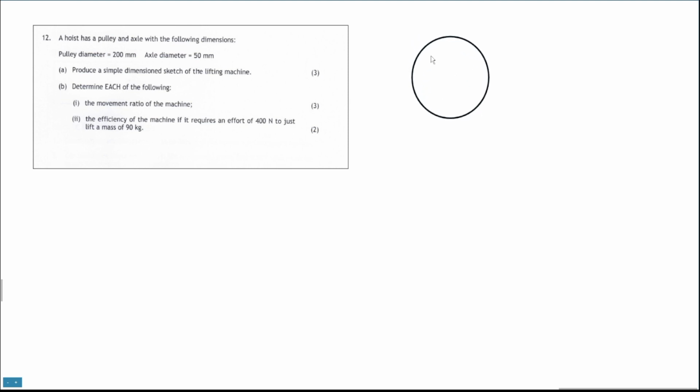So what we're talking about, there's lots of different versions of these. They have them with different combinations. We'll see them in different ways, but they're all pretty much the same kind of thing. They are actually all basically levers. We're talking about a lever, even though it's a circular lever. And what's going on here is we have a pivot in the middle, and we are pulling it on the outside. So you can imagine this like being a lever, and imagine you're pulling it here or lifting it, and you'll be lifting the load right here.